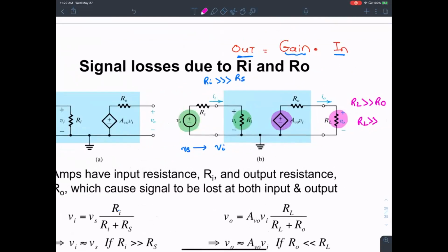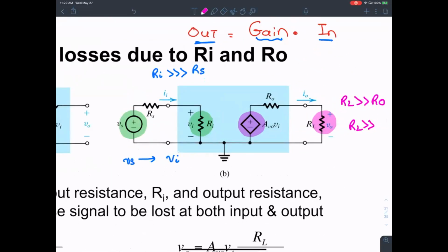In the back of your mind, what you're thinking is, where do I want the maximum voltage showing up? This is just a parasitic resistance. Ideally I want it to be 0. I don't want any signal lost in that. Any voltage that I apply here gets multiplied. Any voltage that is dropped here doesn't translate into a gain, because it's simply dissipated. Only what you see here is multiplied there. Therefore, you want the most voltage showing up here. So of this voltage, you want a lot of it showing up here.